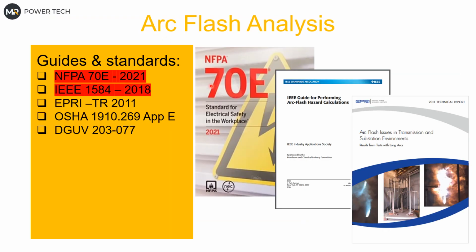And to know your numbers, you need to go through usually NFPA 70, IEEE 1584. Those are the main things. In 99 out of 100 cases I will do it on IEEE 1584. If we are outside of the boundary of the equation, and that's something which I have to mention now, how far we have to go with this analysis.